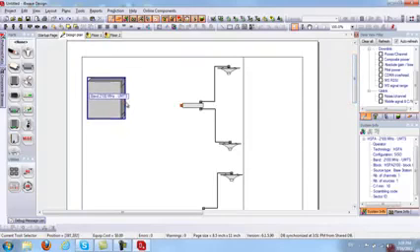And I want to connect my base station to both my floors, so I would need to split the power. I can create a splitter like I did before, or I can use the clone stamp tool button, and I can clone just about any component. So I'm going to go ahead and clone my splitter, and I can use this splitter here to make the connection. I can also clone my cable and make basically the connection.